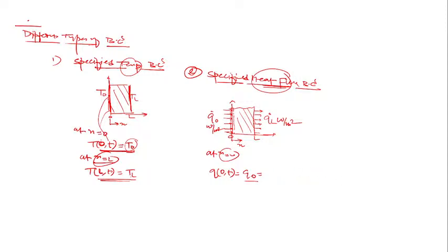Now at this point, whatever heat is going to transfer through the heat flux is going to be conducted in this solid by conduction. If I assume a control volume at this surface, then whatever heat flux is there, like Q naught, the same is going to be transported in the solid wall via conduction, minus K into dT upon dx at x equal to 0. Yes or no? Tell me please.